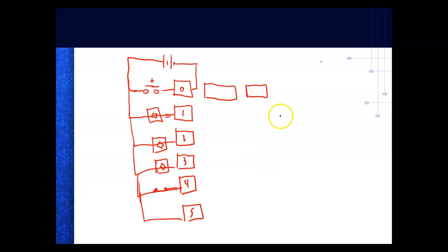So I come over here, so this would be my 2 rungs. Everybody okay? And then I would come over here and use this right here. And then I would want to address this. I'd say input, right? Everybody okay? Then I put a what? Colon. And then I give a module number. Well, since the CPU does not occupy a slot, all our modules are going to be 0.